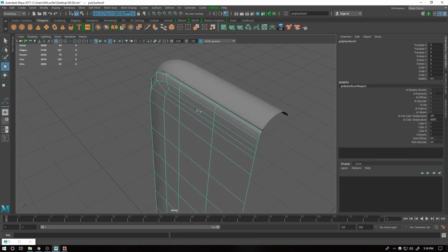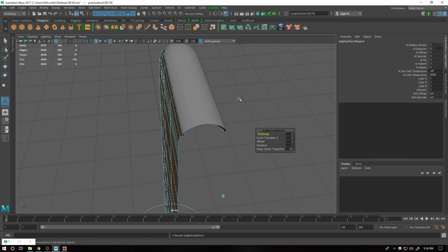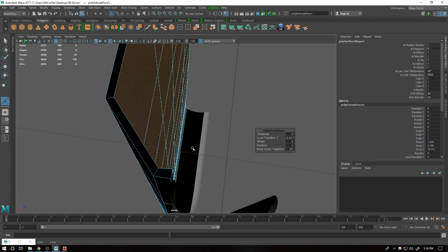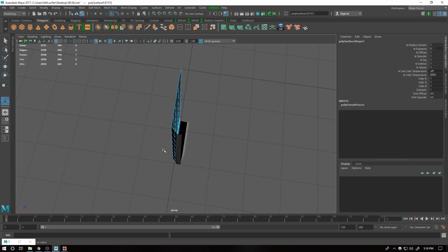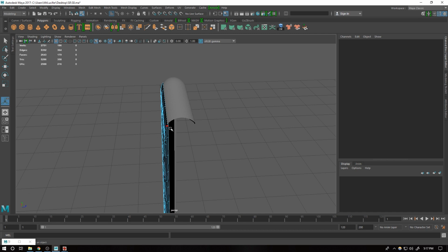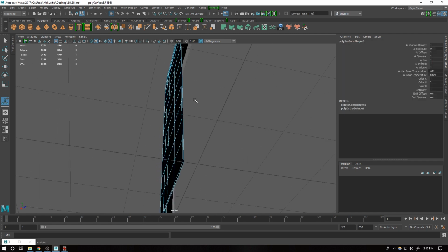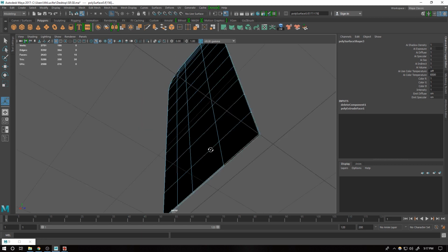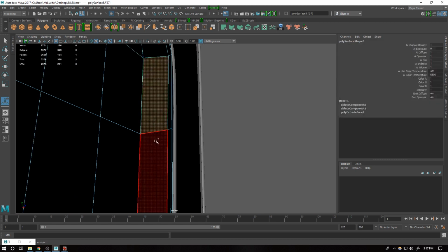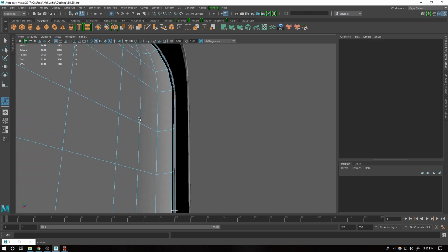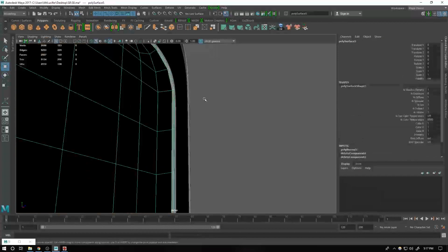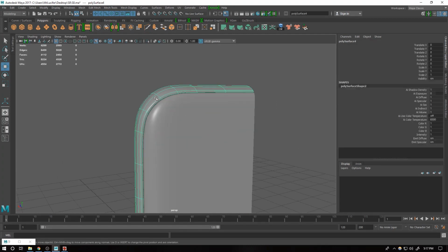Okay, now I'm going to give thickness to my screen also, a little bit of thickness towards the middle. Delete this one, delete from this to this one. Now delete the inner sides and reverse. Shift right click, face, reverse face, face normals, reverse face. Now if I press 3 and 3.